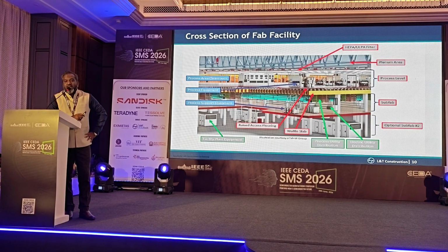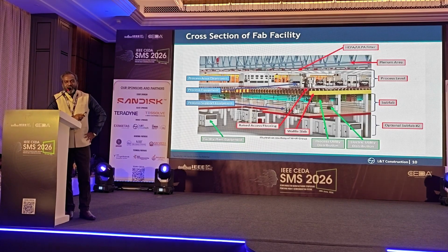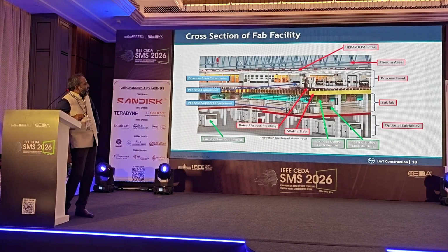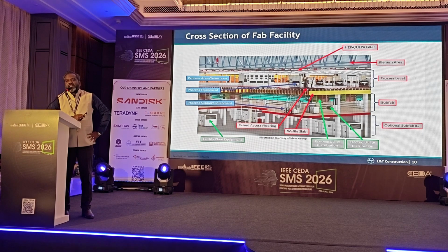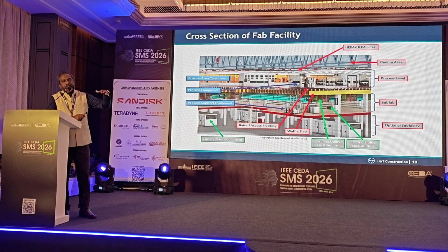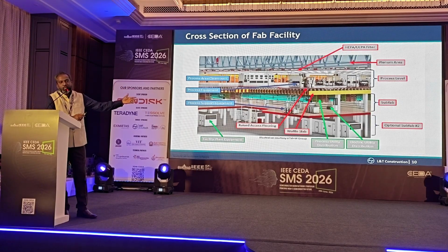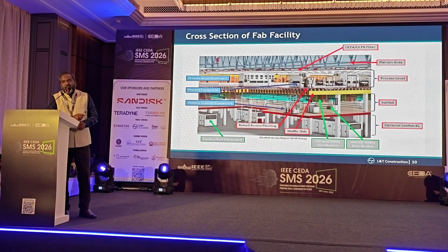Certain tools could have as high as 180 utilities connecting to the tool. I'm talking about 180 different types of utilities connecting to the tool. So we will have to make that happen. So the place is full of holes. And this also acts as a plenum or a shaft for the air to flow from L30 to L20. That is why I say L20 is a clean subfab.